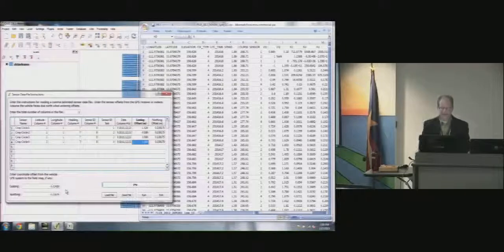And that system was used to make the plot map. So we have some issue there because we've used 2 different RTK GPS receivers to make the map and to collect the data, and there's some offset between the 2. So I have included this piece down here where you can specify what those offsets should be between the 2 systems.